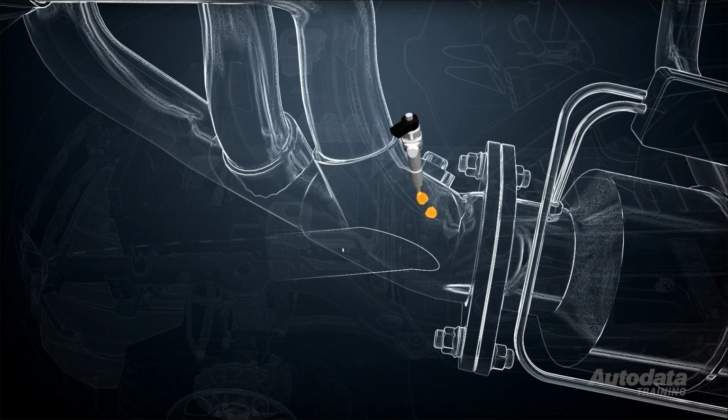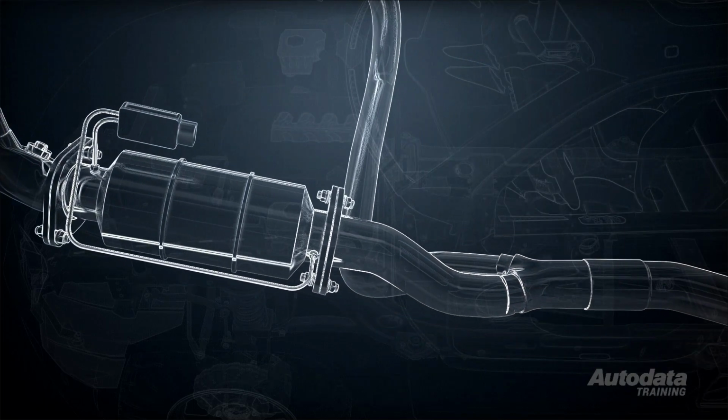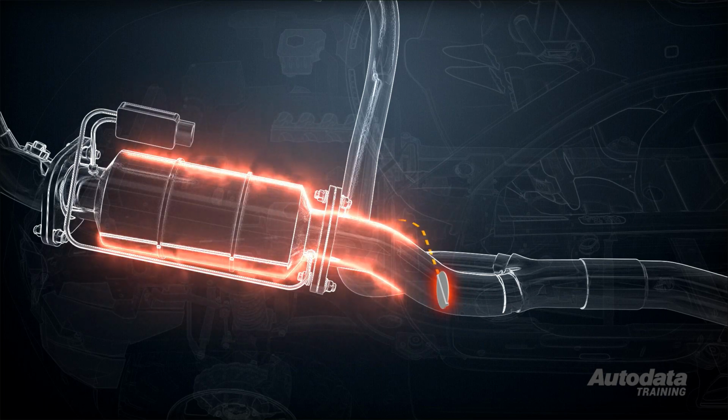Manufacturers can either use a simple injector or incorporate an air supply as well. A spark plug may also be deployed to initiate combustion. Finally, some OEMs place electronically controlled flaps in the exhaust to create additional back pressure. This generates the higher temperatures required for a regen.